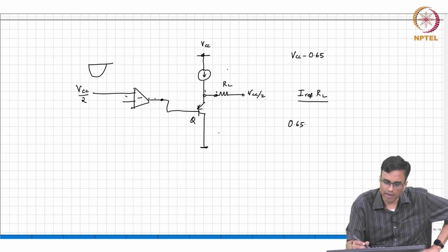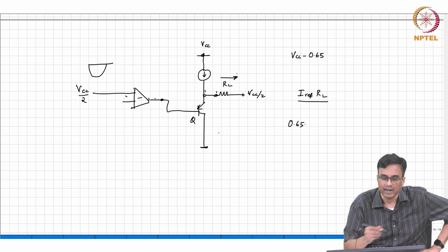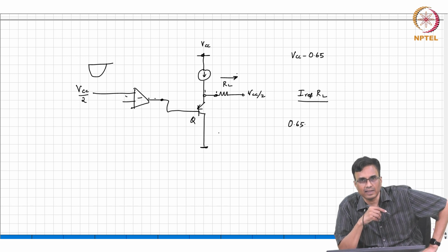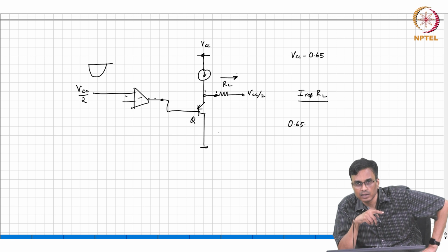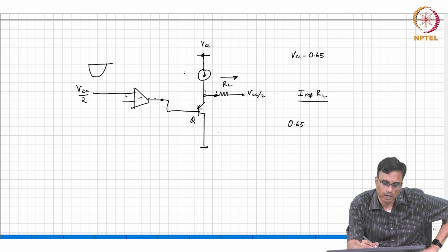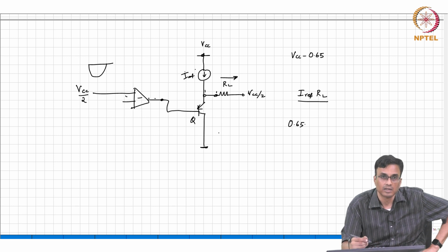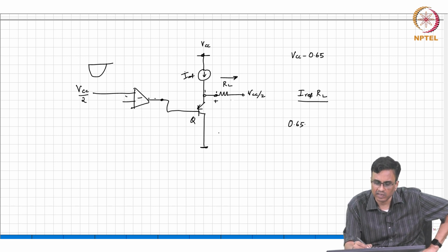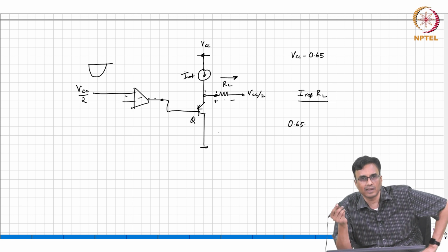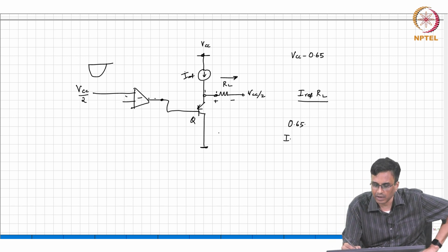When in the positive half of the input cycle, current is flowing that way. So, the transistor is in danger of going into the cutoff region. So, what is the maximum swing? The maximum positive voltage across the RL is basically IREF times RL.